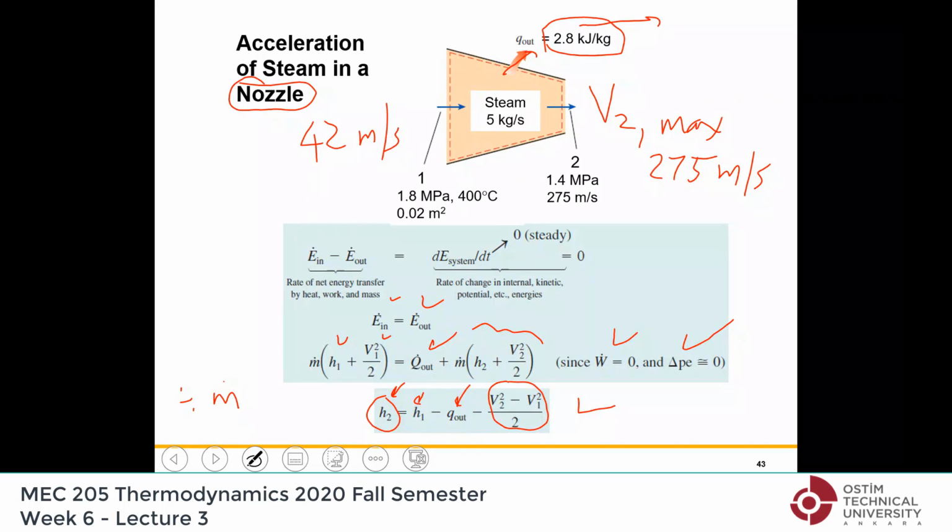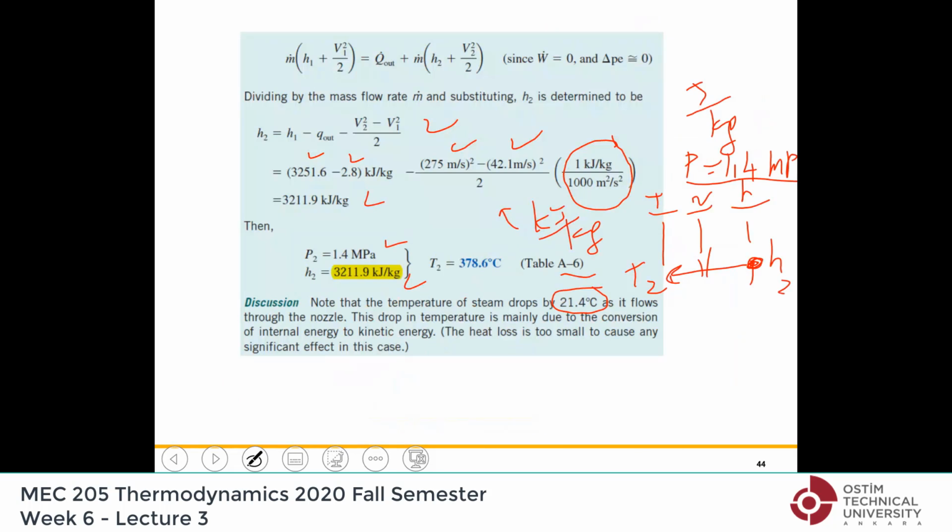What we do is, assuming the process is perfect, that is, there is no heat loss and also no friction here, then we compute the ideal velocity, the highest possible velocity, and compare it to the actual exit velocity. We will do this in chapter 7, so you will see how the efficiency of the nozzles is defined there. But basically it is related to the actual exit kinetic energy divided by the maximum possible kinetic energy at the exit under the given conditions. Other questions?